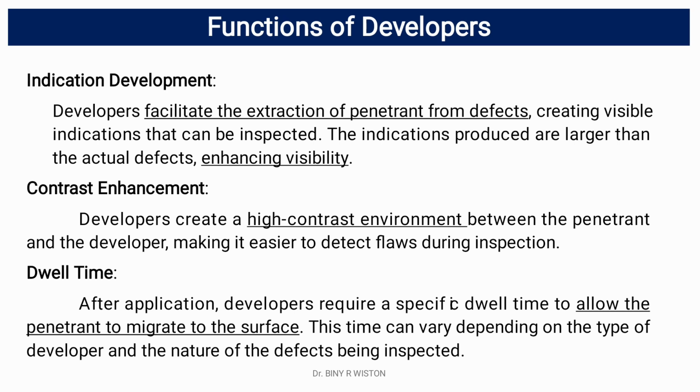Developers create a high contrast environment between the penetrant and the developer, making it easier to detect flaws during inspection. After application, developers require a specific dwell time to allow the penetrant to migrate to the surface. This time can vary depending on the type of developer and the nature of the defects being inspected.